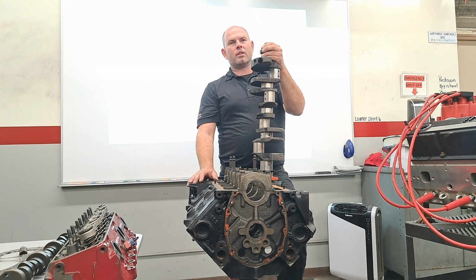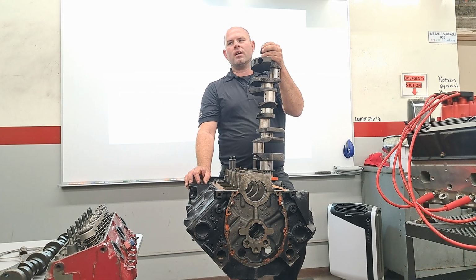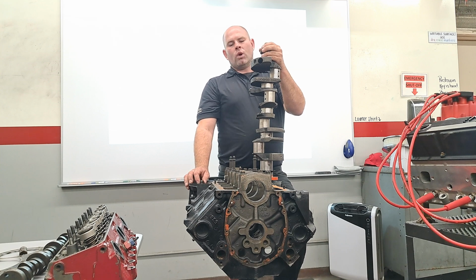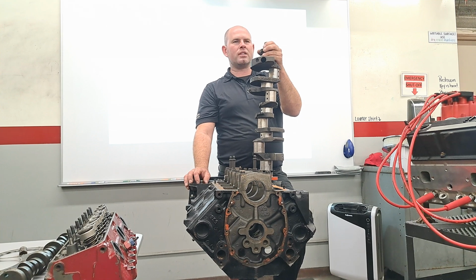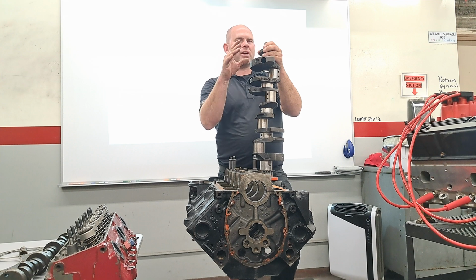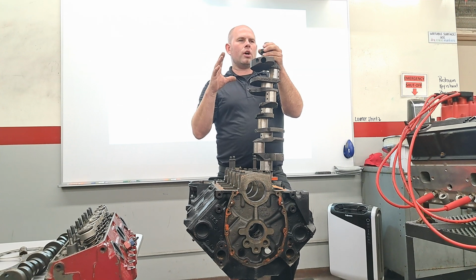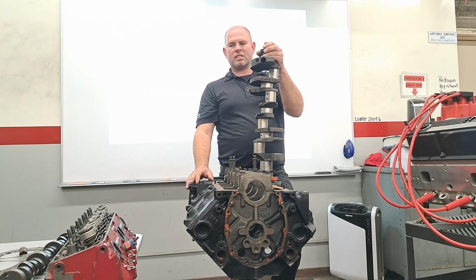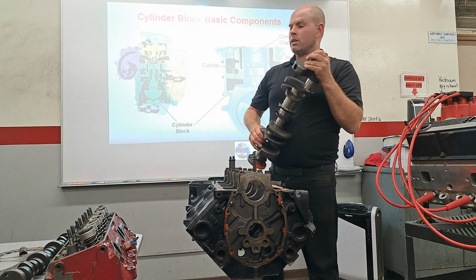If you ever had to line bore it, that's a big deal. Like that's not like, oh yeah, we're just gonna do a quick line bore. Not that many places are gonna do it. Once you do, you're gonna be into it for larger bearings because you can't line bore at the same size. Otherwise you're gonna be missing some, right? So you gotta go bigger. If you have to go bigger, you have to do what's called an oversized bearing. So this is something that people can tend to struggle with. So I'm gonna drop this down for a quick second about oversized bearings.